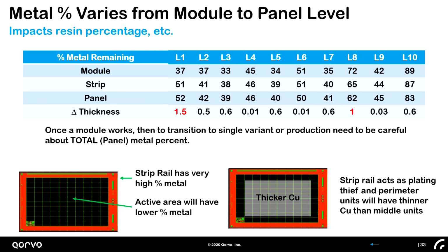So there's that, and then across the strip, because of the local pattern densities, you can have thicker metal in the center and things like that. So when people are like, oh, well, I only measured one, it's like, well, you should probably measure some of them in the areas you think they're going to be different in, because we would try to ship stuff from here. So you better test all of the possible places where there's the metal thickness. Don't assume it's perfectly uniform.